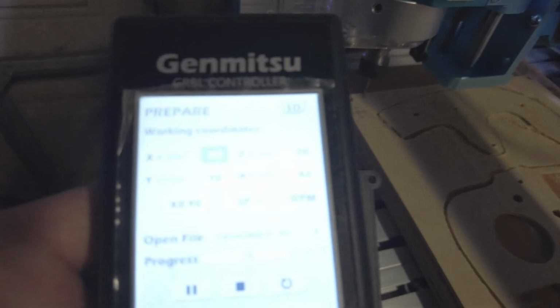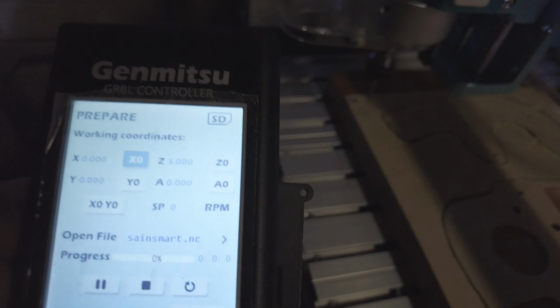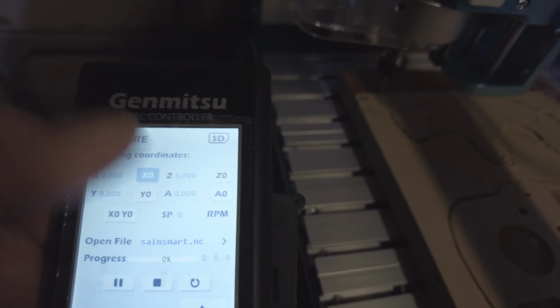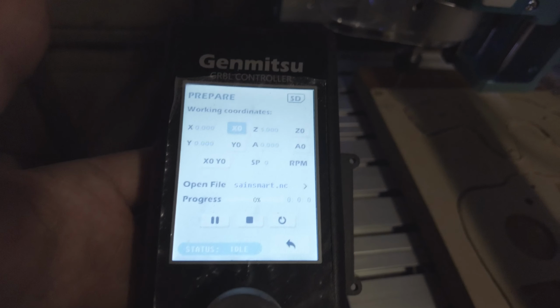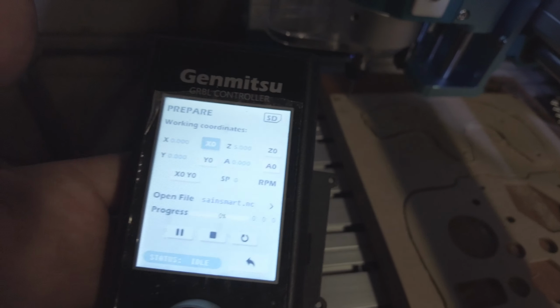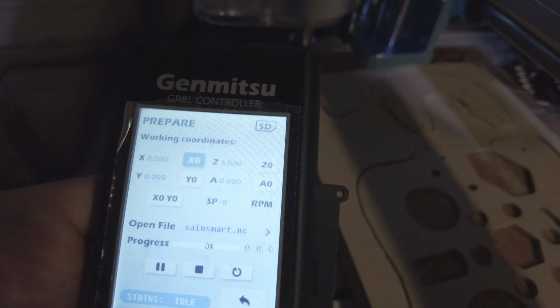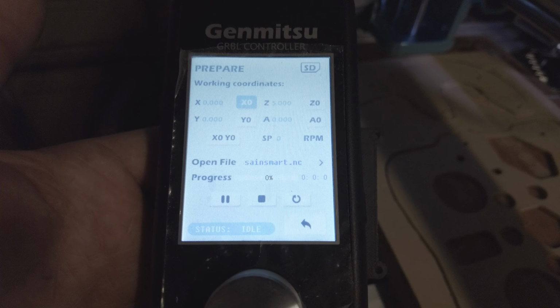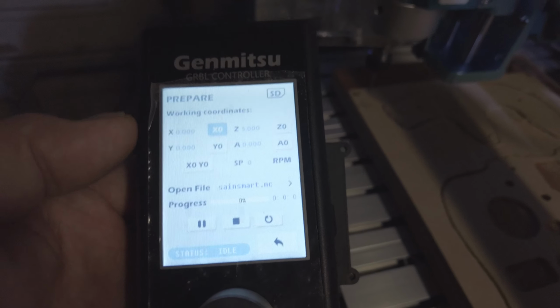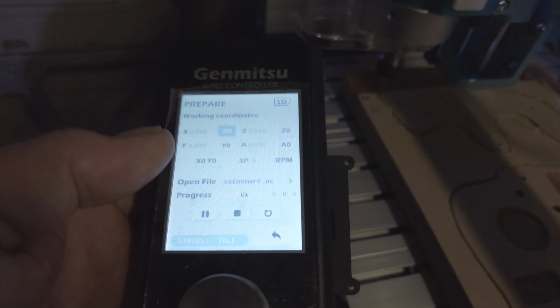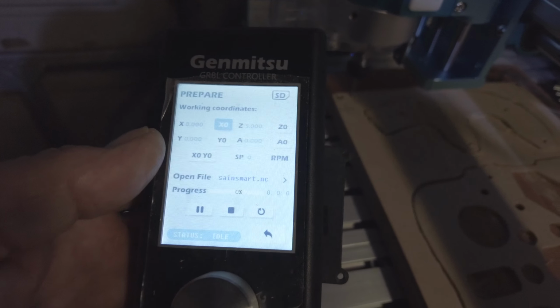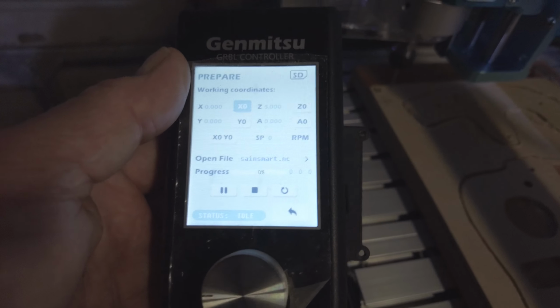There we go, finished. Back on your 0, 0, 0, and your z-axis shows 5 there. It's back, same coordinates. So now if you wanted to put another toolpath in, you would do the same. I just hope it's made it clear how simple and easy it is to change cutters and install another toolpath.